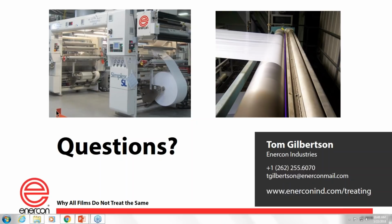What's the difference between a bump treater and a full-fledged corona treater? Well, bump treatment really refers to, you have to start someplace with this example. So we're going to start here. We're going to assume that it's a printing application, and that the film being put into the printing application starts at 36 or 38 dynes, which typically wouldn't be good enough for a water-based printing application. Maybe for water-based printing we need 40 or 42 or 44, it depends on the ink chemistry, but somewhere in that range.